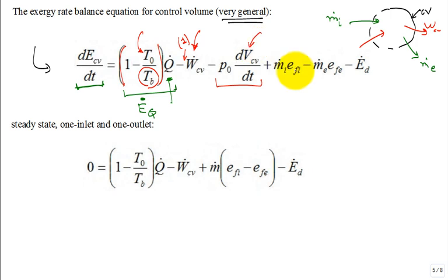All right. Then we have, actually, this probably messed up on the subscripts. I have to include that term in there and then subtract it off. All right. This is a mass flow rate with the flow exergy in. This is the mass flow rate with the flow exergy out. What? It's a different exergy. It's a flow exergy. It's just like enthalpy was a flow energy. It accounted for the flow work. We have a new exergy. It's called the flow exergy. And then you have exergy destruction.